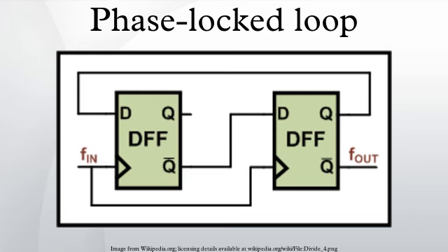For example, by changing the operating frequency up and down by a small amount, a device running at hundreds of megahertz can spread its interference evenly over a few megahertz of spectrum, which drastically reduces the amount of noise seen on broadcast FM radio channels, which have a bandwidth of several tens of kilohertz.